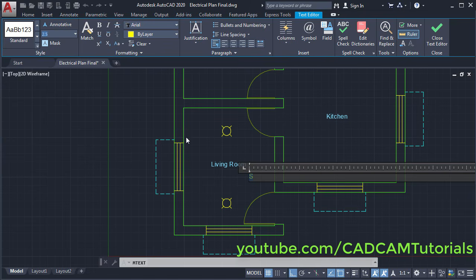In my case, the width of this wall is 300 mm. So if I want to make this character of this much height, then I will have to specify 300. And if your base drawing is in a different unit, then as per that you will have to choose the height of the text. So in this case I will choose 200, enter.